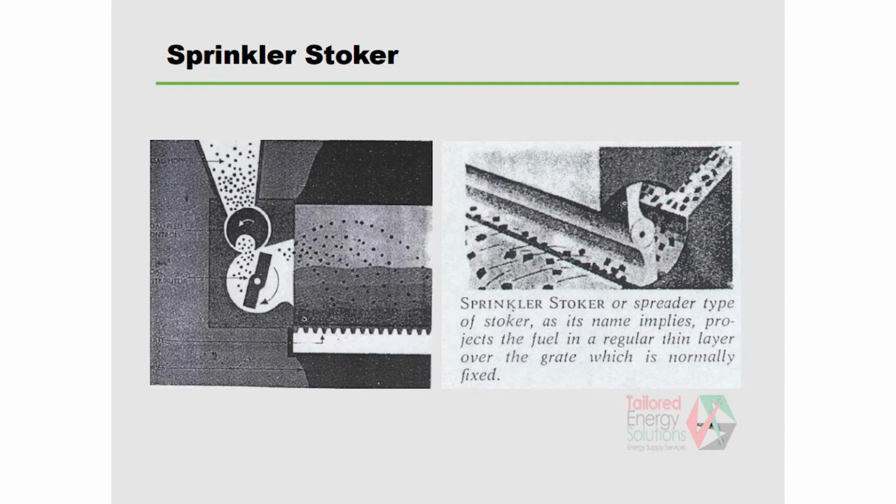Sprinkler boiler. The sprinkler boiler is probably very, very common now because of boiler sizes getting bigger. The coal comes this way and drops towards a sprinkler, a rotor, feeding the coal onto the grate, with combustion air coming from the bottom. So that is the way.